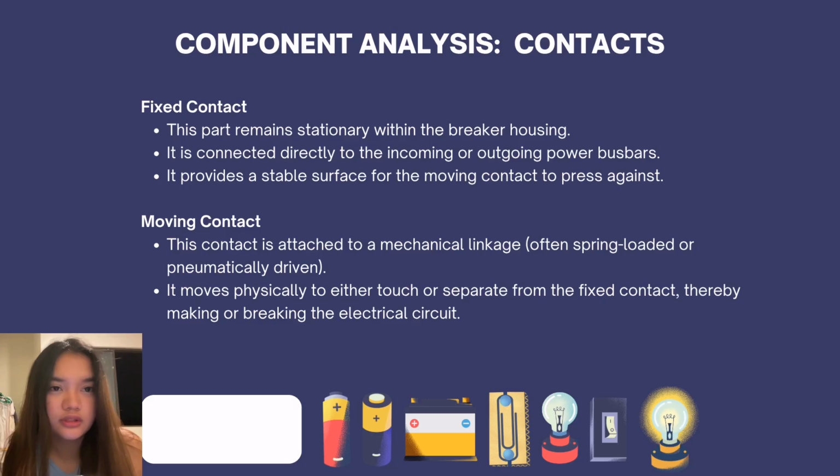The other one is the moving contact. This contact is attached to a mechanical linkage, often spring-loaded or pneumatically driven. It moves physically to either touch or separate from the fixed contact, thereby making or breaking the circuit.